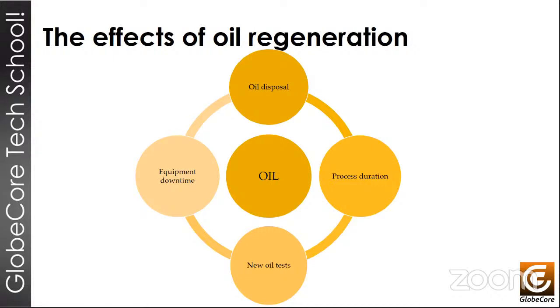Another important thing is there is no need for a long wait for the paper to be permeated with oil. We don't need to reduce the oil level of the transformer. Another point in favor of the regeneration process is the effect it has on the contaminants in the transformer windings, and I've mentioned this before.